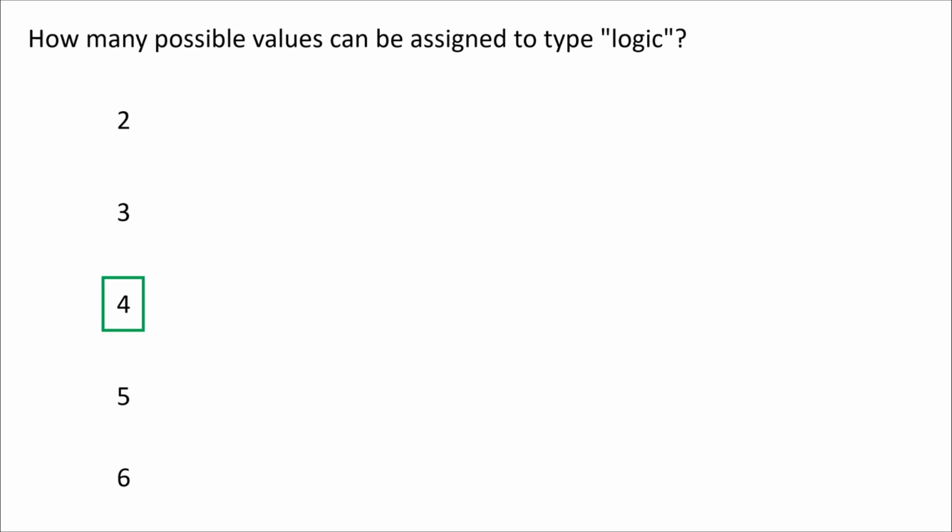Oh, well, actually, so input and output, that's a good question. Input and output isn't a type in Verilog. It's like a modifier. It's used for defining inputs and outputs to modules. The basic type that we're using is logic. And I mentioned a few minutes ago there's another one called tri. But we're just using logic in this course. And there's actually others even beyond logic and tri. I think you can have one that's like a floating point number. I think it's real, if I remember correctly. There's integer. There's some others, but we're just focusing on logic because logic is synthesizable.